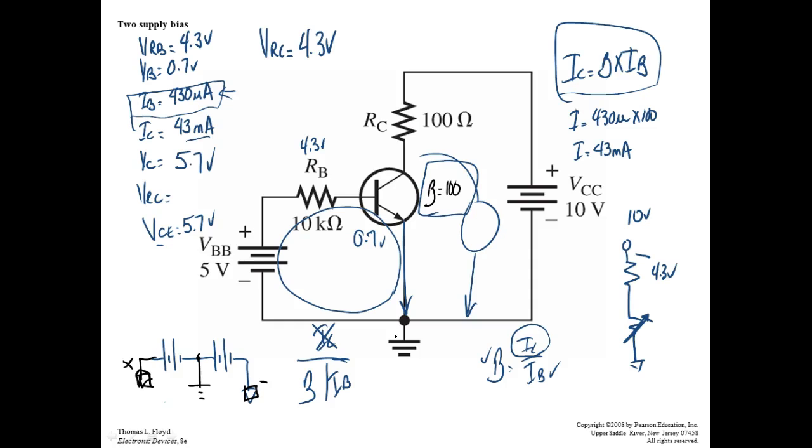So I can't use the power supplies on the trainer. So what are we going to have to do? We'll have to use an external power supply. We'll use one of these right here, like that I use. We can't use the two variable power supplies on this that are connected the same way. But what we can do is use one of the trainer's power supplies, connect the commons together, right? And then we can use that. So this is one of the circuits we're going to use. But pretty soon we're going to move into a single power supply bias situation.